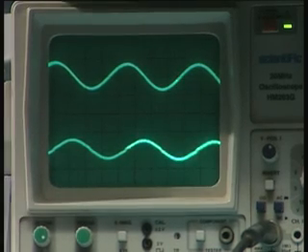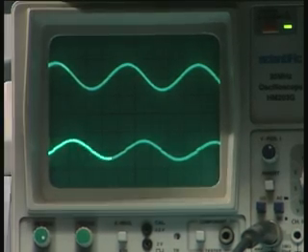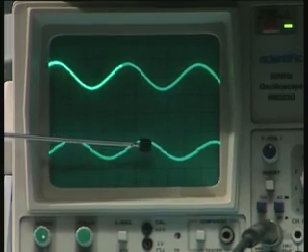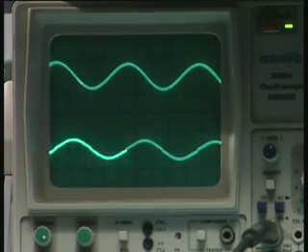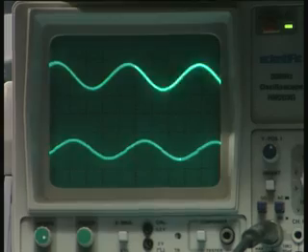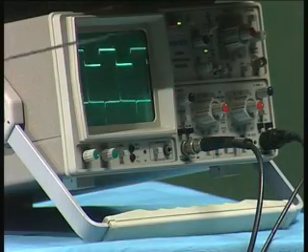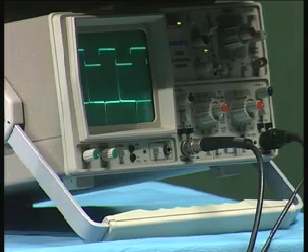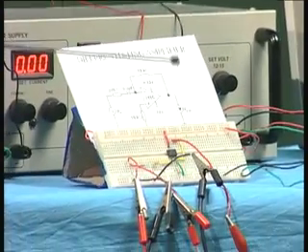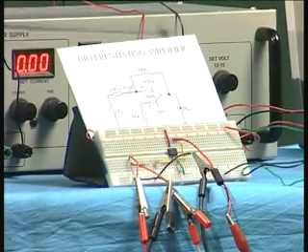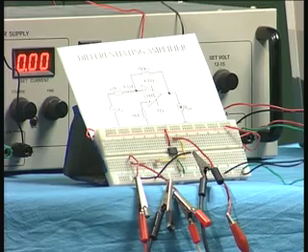There is a relative shift, and that corresponds to the cosine wave. The bottom one is a cosine wave, the top one is a sine wave. I will again come back to the square wave, and you can see the spikes. So this circuit performs what is known as differentiation of the input signal with reference to time.